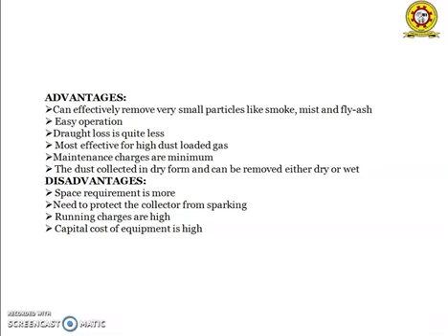The advantages are that they can effectively remove small particles like smoke, mist and fly ash. They are easily operated. Draught loss is quite less, and they are more efficient for high dust loaded gases. Maintenance charges are minimum. The dust is collected in dry form and can be removed either dry or wet.